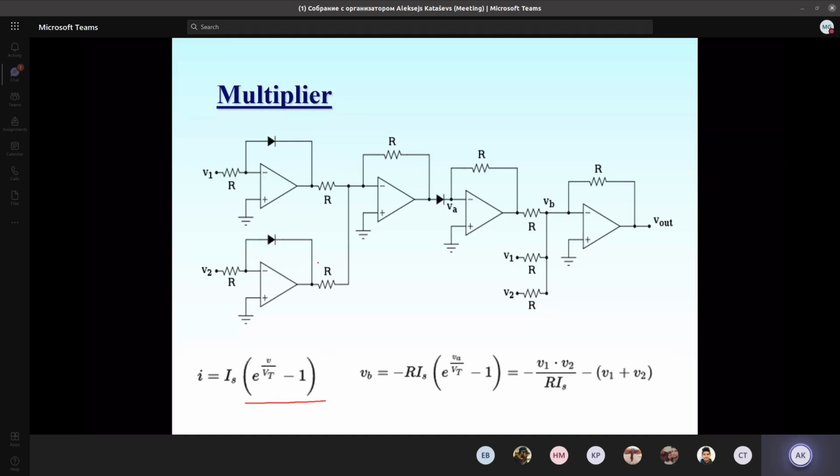As both logarithmic amplifiers are inverting and the summation amplifier is inverting too, when the signal is positive here, it becomes negative after the logarithm operation, and becomes positive again after summing. So here we have a positive voltage, and here we have an anti-log amplifier with the diode at the input.